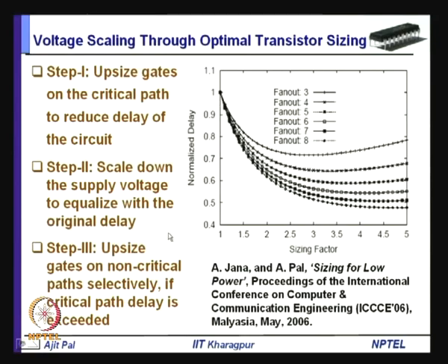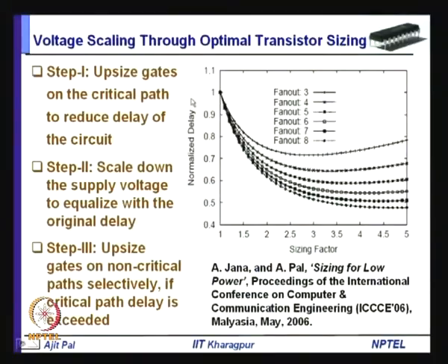Obviously, whenever we do this, there will be increase in area, because wherever we are upsizing, there will be increase in area. That means, here again we are trading area for lower power by this technique. Okay. So, this is the second technique that we can do.